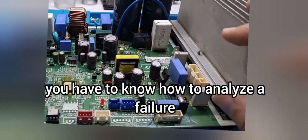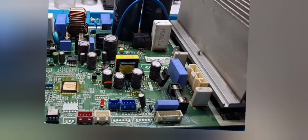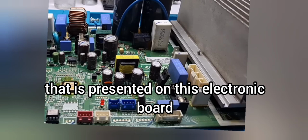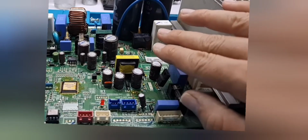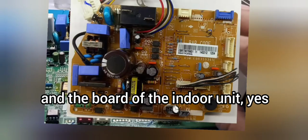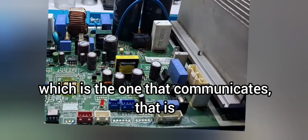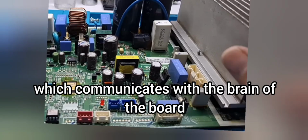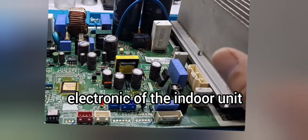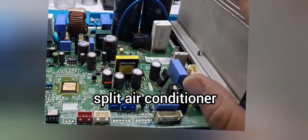In the first place, you have to know how to analyze a failure. The client tells us that the error CH5 presented on this electronic board is due directly to an intercommunication failure. Intercommunication between what? Between the outdoor unit and the board of the indoor unit. Here we have the integrated circuit of this outdoor board, which communicates with the brain of the electronic board of the indoor unit. They are the two that command the entire operation of our split air conditioner.